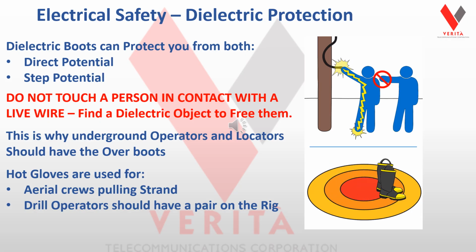Now, on the aerial side, we want our people to be wearing hot gloves when they're pulling strand till it's been tied off, tensioned, and attached to the power company's multi-ground neutral. Okay? And talking about the gloves, operators are supposed to have a pair of gloves on the rig with them just in case.